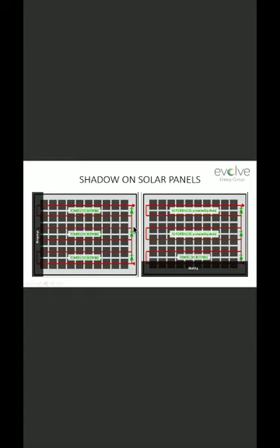So the bypass diode is not engaged, and the power generated by these 18 cells will be consumed by these 2 cells, not fully, but some amount of power is consumed by these cells. So a huge power loss will happen here, and the cell which is consuming power also creates more heat because of the high resistance caused by the falling shadow.